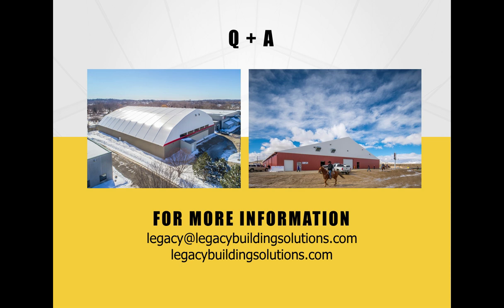Okay, next question. What is the fire rating? So the fabric that is utilized in most applications is required to pass NFPA 701, large and small scale. And I realize that probably doesn't tell you a whole lot. The fabric itself is typically known as non-combustible with a 0-hour rating. And so if you go into the building code book, typically a fabric structure is going to be a Type 2B building.